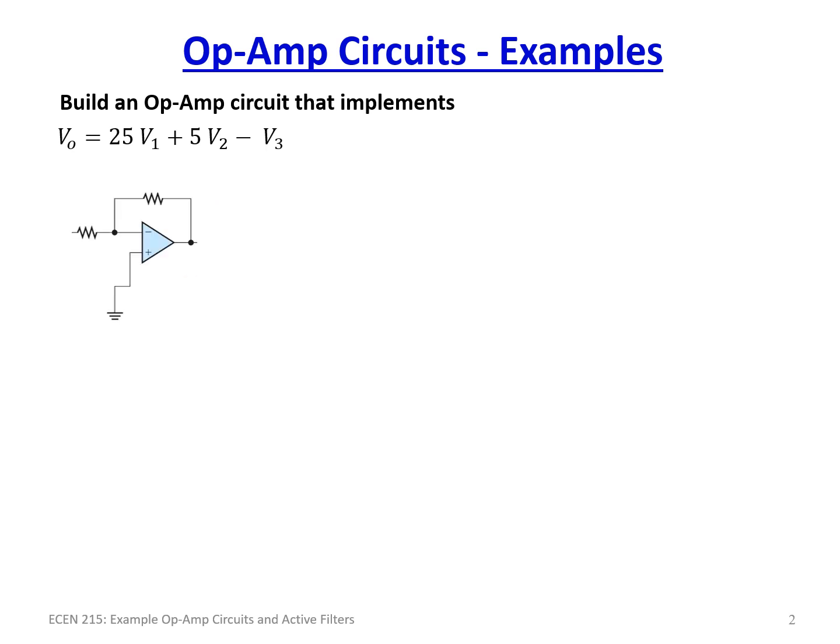Our first stage is an inverting amplifier, and we're going to focus on the input for V1. So this is going to be V1. Now V1 is going to have a gain of 25. We're multiplying by 25. So just so that we have some reasonable impedance, we're going to use 25 kilo ohms here, and we're going to put a 1 kilo ohm resistor here.